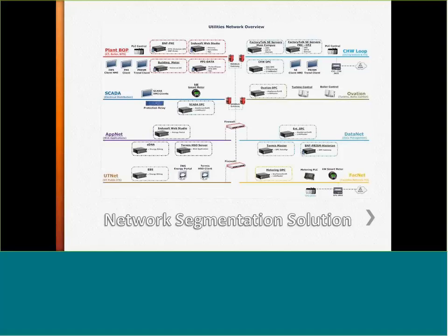The data from those network segments was brought in through gateways that we installed, and after a firewall, this data goes into our enterprise OPC, which is fully redundant. We have Kepware technology. It's an OPC manufacturer and developer, and we have LinkMaster within it.